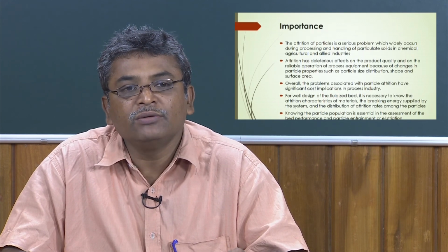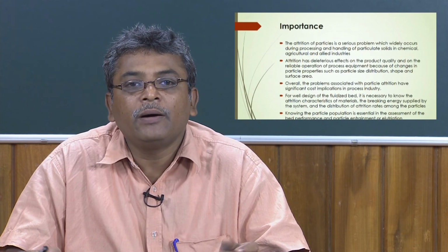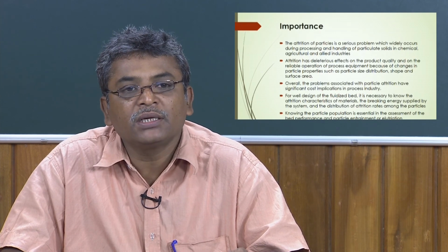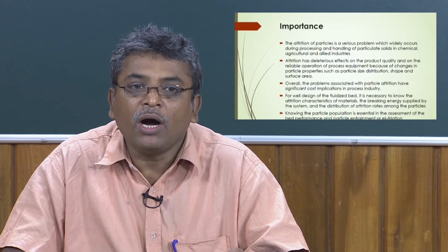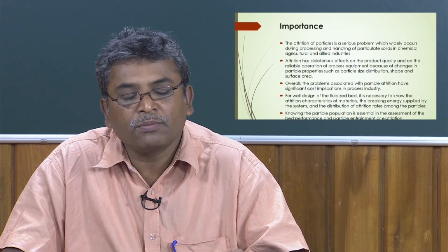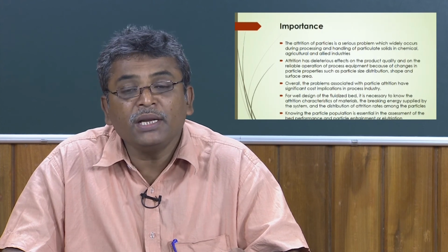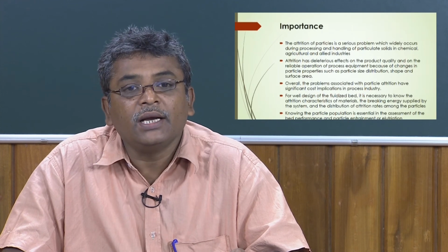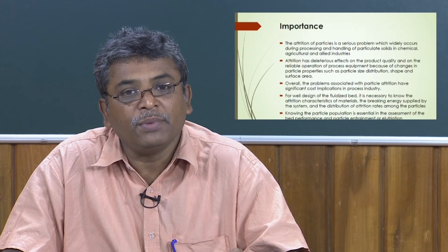Even somewhere you will see, if some operation is well characterized by the fine particles, whereas if you have coarser particles, then you have to know how much coarser particles and how much fine particles will be inside the bed. Based on that you will have to judge what will be the performance of the fluidized bed there.